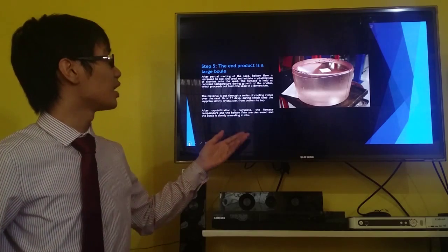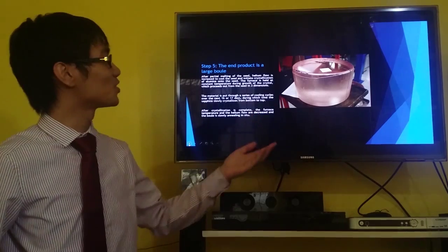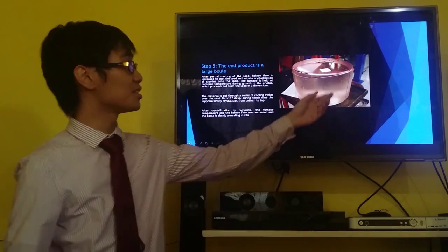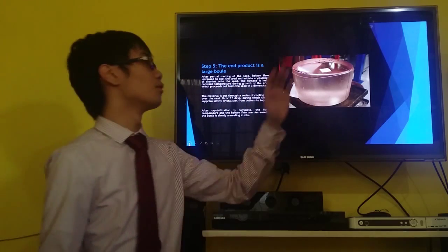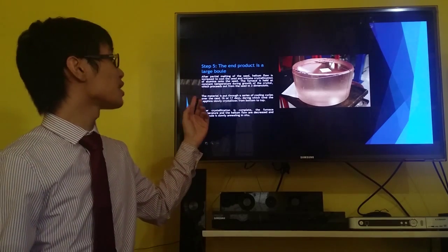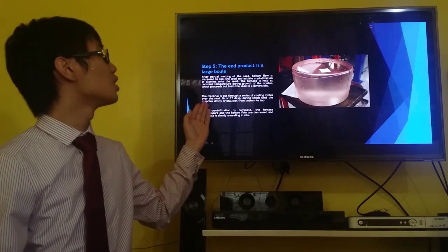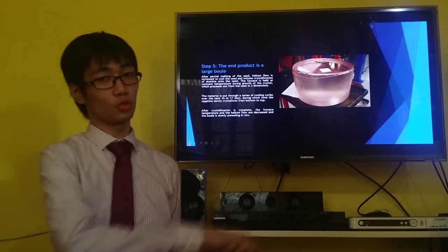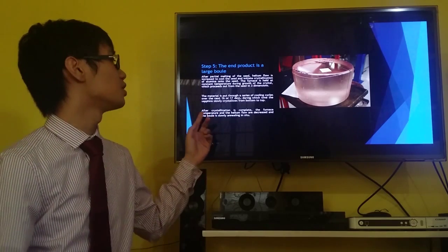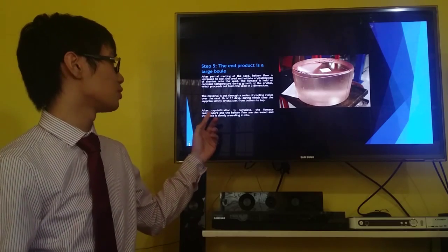The furnace is then held at constant temperature during growth of the crystal, which proceeds out from the seed in 3 dimensions. As you can see, this is a 3-dimensional boule. The material is put through a series of cooling cycles over 16 or 17 days, during which time the sapphire slowly crystallizes from bottom to top. Then, after crystallization is complete, the furnace temperature is decreased by helium flow and the boule is slowly annealed in situ.